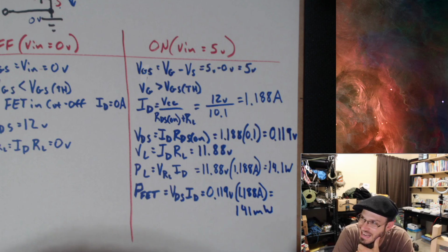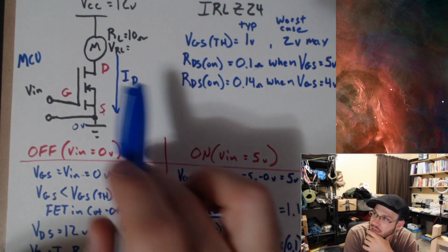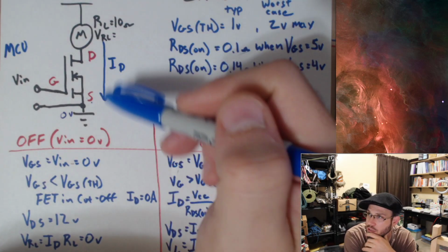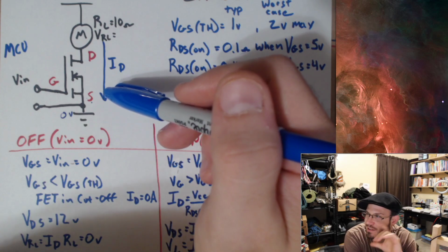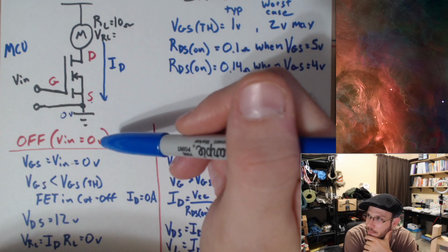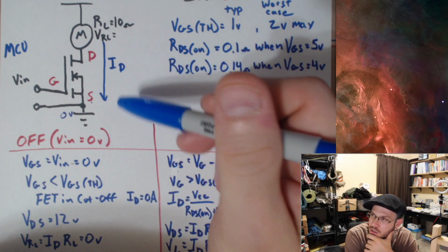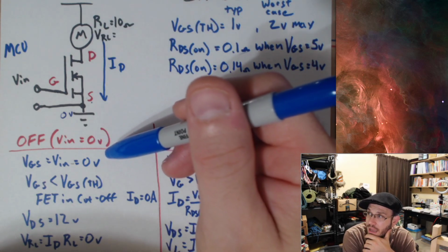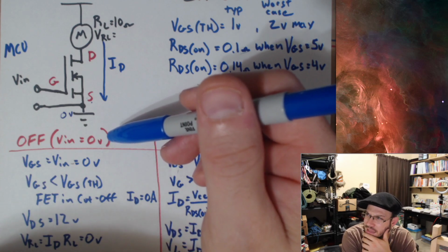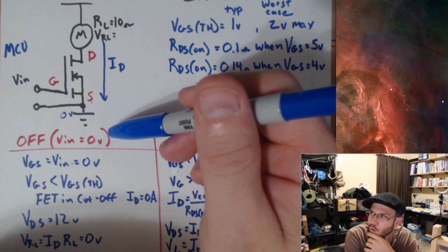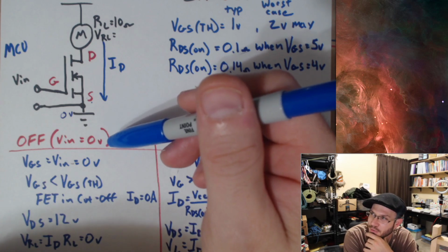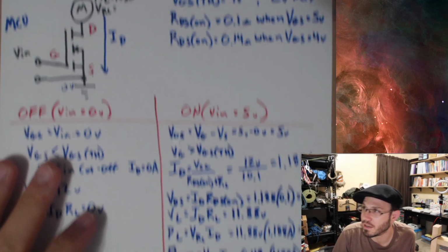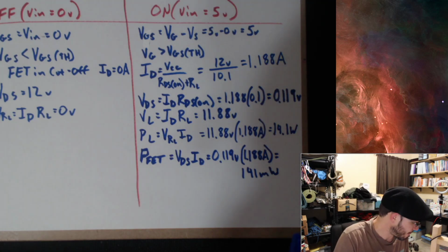Now, in the case of a BJT, good luck. Good luck doing this with a BJT, because a BJT is going to develop a much higher voltage drop between, I got to switch my terminology now, between the collector and the emitter. And that larger voltage drop means if I put 1 amp through there, it's going to be catching fire really quick. Okay. Maybe I'll have to set that up in a future example and blow up one of my 1,000 3N04s for the sake of just blowing up a transistor for fun. Okay.